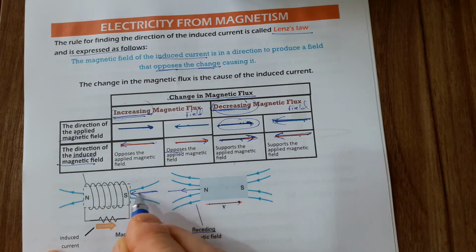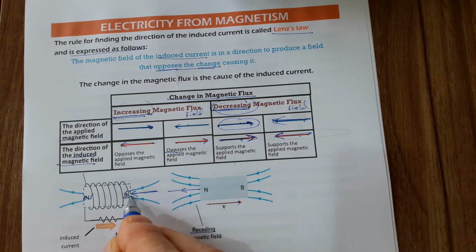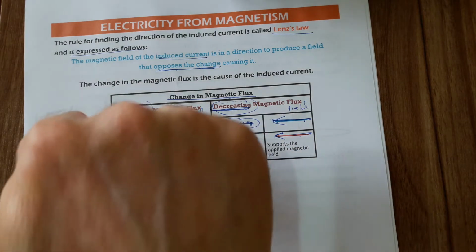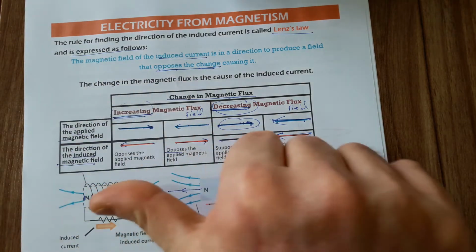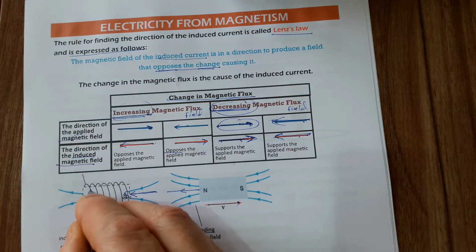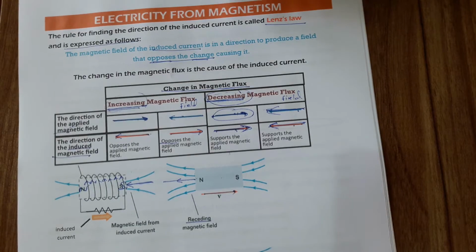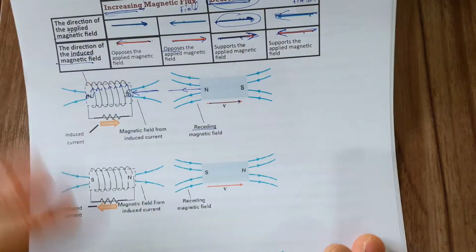So as you see, this is the direction magnetic field has entered from S pole and leaves from the N pole. So this must be S pole in this case. If this is N pole, this is S pole, that is N pole, use the right hand rule so you can understand that thumb points in the direction of the N pole. Curled forefinger is the electric current direction in the solenoid. Okay, so let's apply this to the following one.